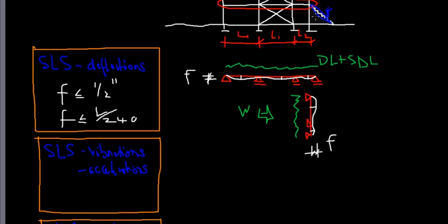And so what you do is you not only check the static deflection limit on these staircases, but you want to make sure that the so-called eigenfrequency, let's call the lowest frequency here, frequency, say F1, measured in hertz, doesn't go to the same range of what a person normally excites when you walk up and down a stair, and that's maybe anything from 1.5 to 3-4 hertz.